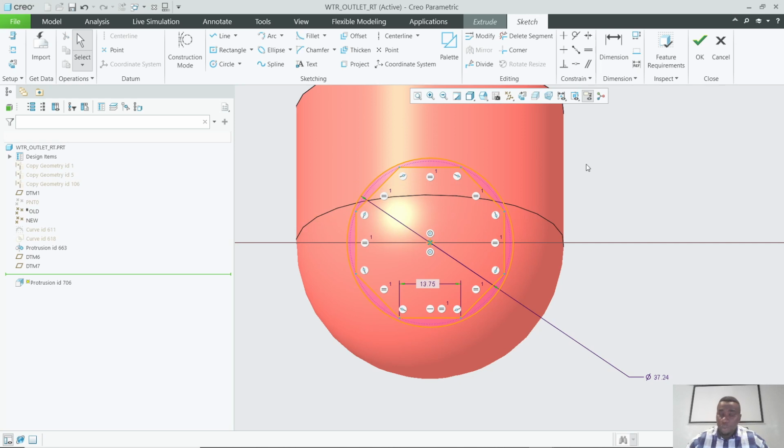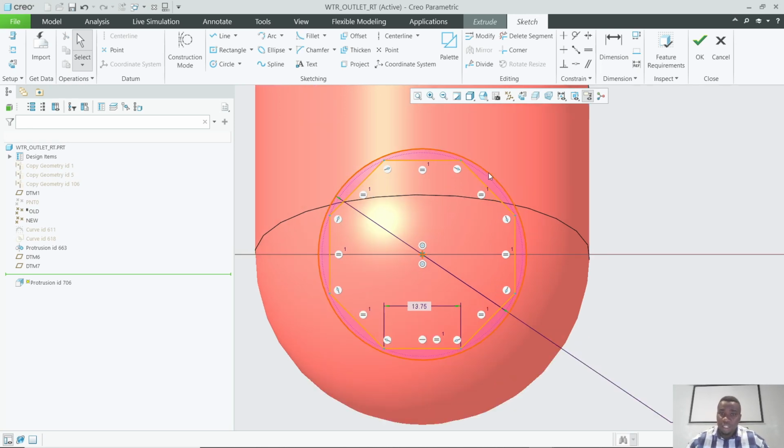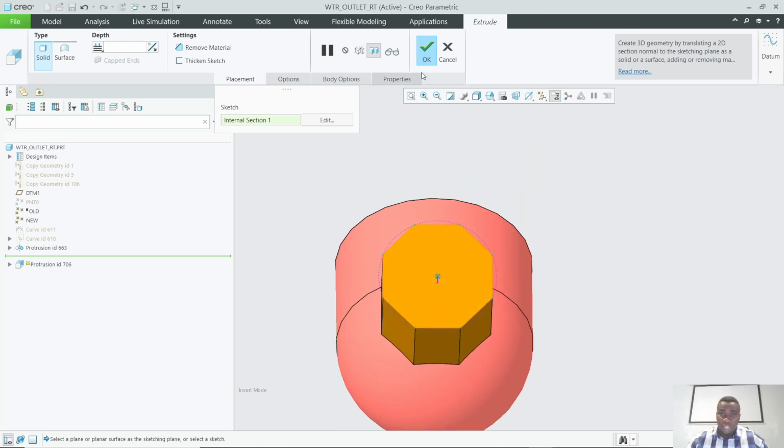So what can one do then? What you can do in this case is say, okay, I want to replace it with that sketch and make sure that all the properties that have been referenced on the cylindrical surface are now shifted onto this one. Why is this important? This is important because now this one will not fail. Those rounds that were on the cylindrical shape will be on the new shape, and your part will be reconstructed correctly with no failures. So sometimes failures can be prevented ahead of time.